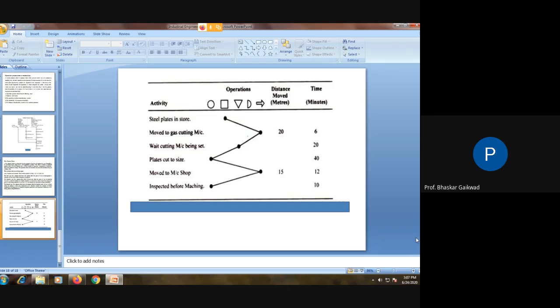Now we are doing the method study. Is it possible to reduce certain operations? Is it possible to reduce the inspection? Yes. So washers we can manufacture in two ways, by progressive dies and by what we call compound dies. Compound dies means at a time both operations, piercing and blanking. And second, progressive means initially we have to go for manufacturing of the ID of the washers, then we'll go for the OD of the washers.